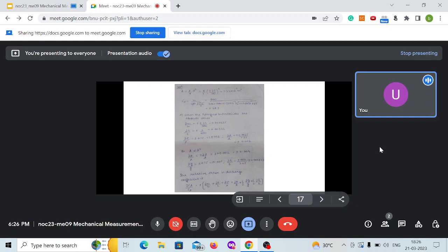Then with respect to acceleration due to gravity, you get plus or minus 0.1%, so it's 0.001. And same with respect to head, we know the values for head uncertainty and head, so it's 0.00082.